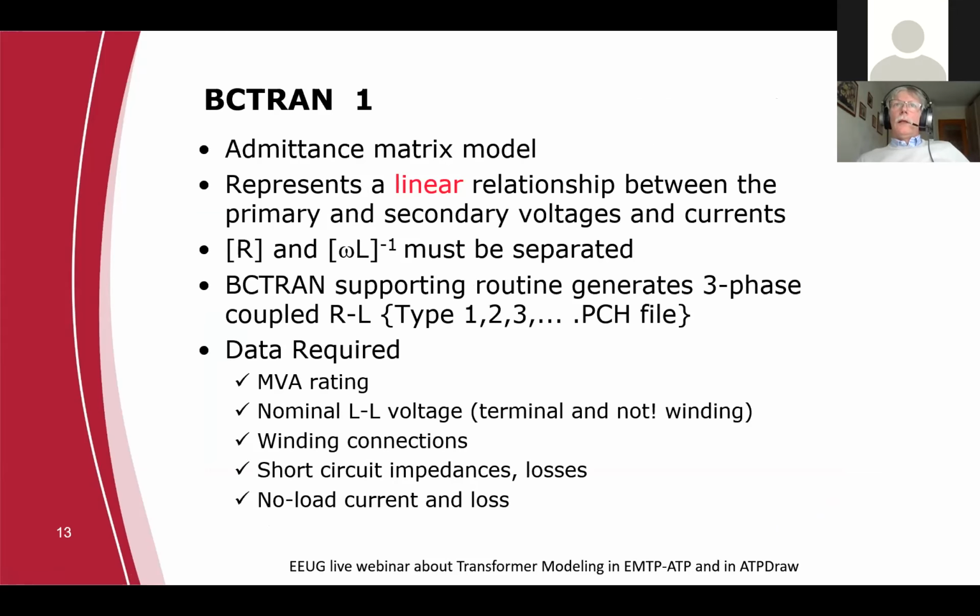The BCTRAN model is more sophisticated. Basically, originally, the BCTRAN model has been, and still is, a linear relationship between the primary and the secondary voltages and currents. So the original BCTRAN is a linear transformer model. If you would like to simulate nonlinear phenomena, you have to complete this linear model with objects capable of considering the nonlinearities.